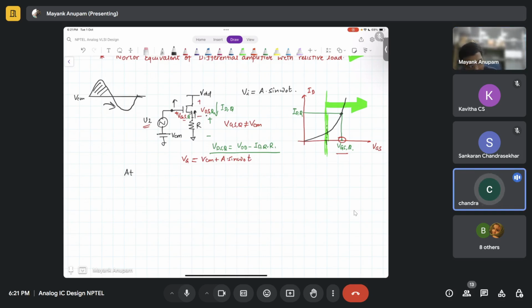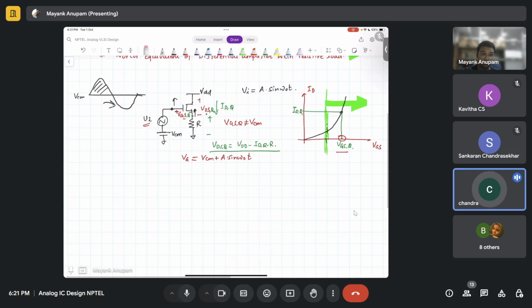I just wanted the process, right? Whenever we see a new circuit, what we essentially have to look at is the input variation and the relationship between VDS and VGS. Then we have to systematically decide whether it's going from saturation to linear or saturation to cutoff. Depending on the configuration, in some circuits when it increases we'll use the saturation to linear one, and in some circuits when it increases we'll use the saturation to cutoff one. Yes, exactly. That's all I wanted.